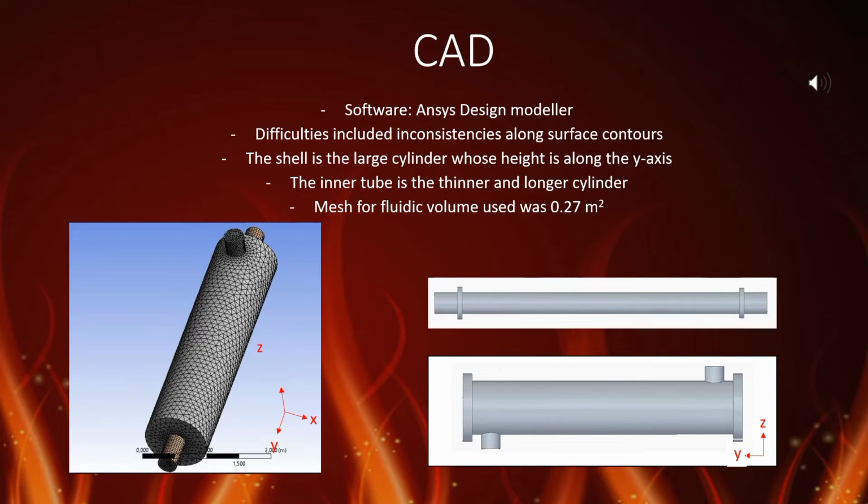The material selected for the shell is aluminum and the material selected for the inner tube is copper. Aluminum was selected based on what was seen from tutorials on heat exchangers earlier in the course. However, we recommend the use of steel for the shell geometry because of its lower thermal conductivity. This decision would result in less heat transferred to it, thereby minimizing heat loss from the fluidic system for the purpose of the previously mentioned application.